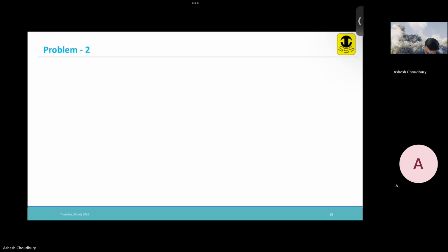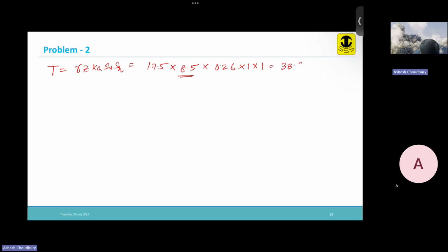Now, right? So this is at the bottommost depth. Okay, 8.5 meter depth. Okay, this much is my tensile load. This much is the load that is coming. Okay, at the bottommost reinforcement, this much is the load that is coming. It is 38.68 kilonewton per strip. Means at the bottommost strip, this much kilonewton of load is taken.